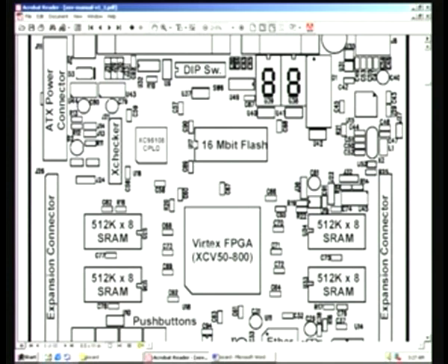We can put a huge circuitry inside this. Our application is going to reside here. It is going to come through this parallel port right onto this FPGA, and we are going to download a dot bit file. For example, if it is a traffic controller, we are going to generate a traffic controller dot bit file by using place and route, and that particular bit stream we are going to download onto this.